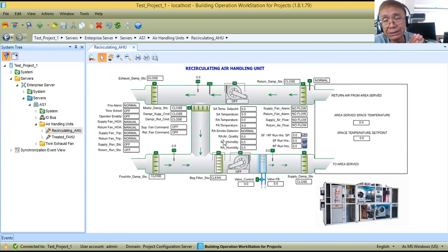Okay. Now let's say the control voltage approved by the consultant is 220 or 240. Now you need to provide, as a BMS engineer, separate relays in your DDC panel to close this 240 control voltage.